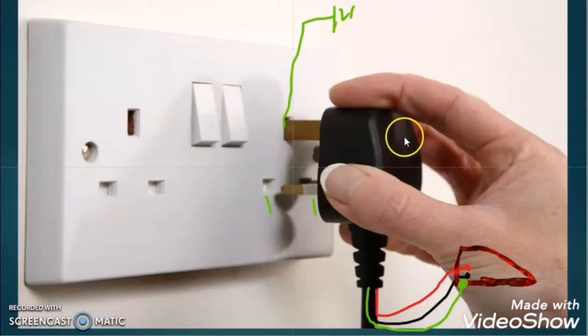So what we observe here, when we are inserting the plug with the 3-pin socket, first the earthing is establishing the connections, and then the phase and neutral supply point are establishing the connections with the load. As the earthing pin first establishes the connection with the earthing point, the body of the load first gets earthed, and then the power supply is reaching the load.